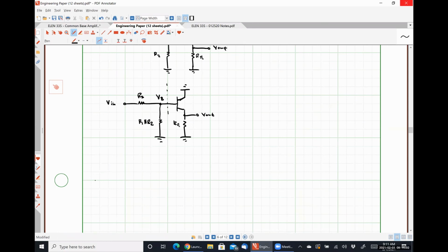Very abbreviated version of intrinsic gain is just the gain of an amplifier circuit where it's unloaded, meaning if we looked at an emitter follower circuit, we would be figuring out what the gain is when RC approaches infinity. We're literally saying disconnect all the biasing resistors and tell me what the gain of the network is. So it's a fairly straightforward topic.